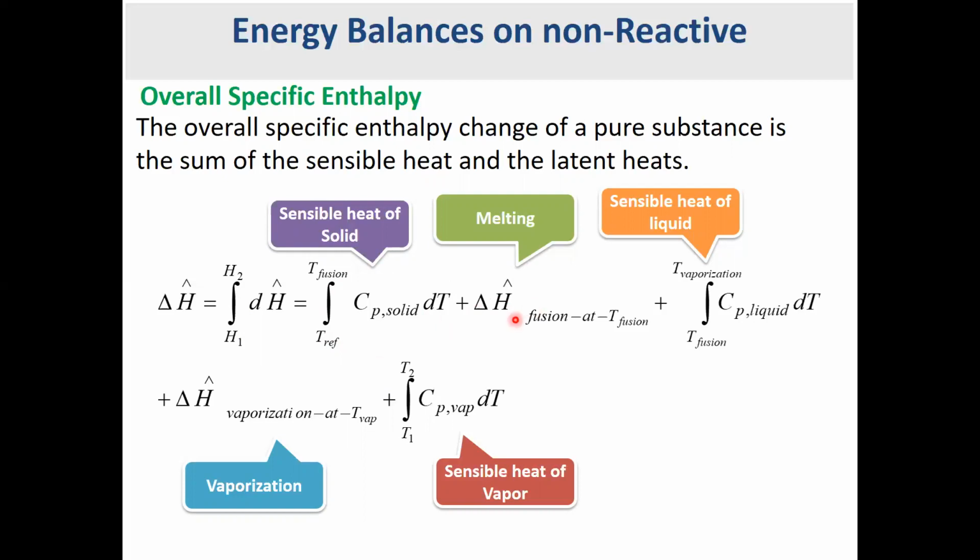After that, you have a phase change from ice to liquid. So you have the melting point. This amount you can find in Table B1 at the end of your book. After it melted, you have to increase the temperature at constant pressure up to the boiling point. So this is the way you can quantify. After that, you have another phase change, that is vaporization.